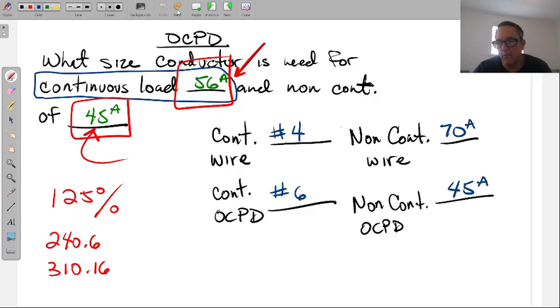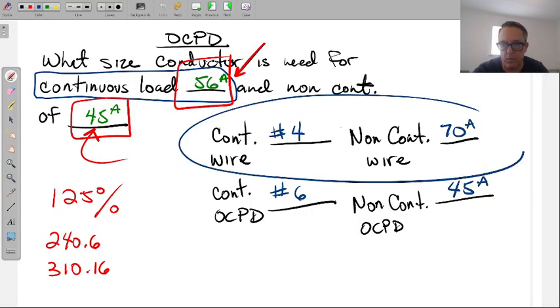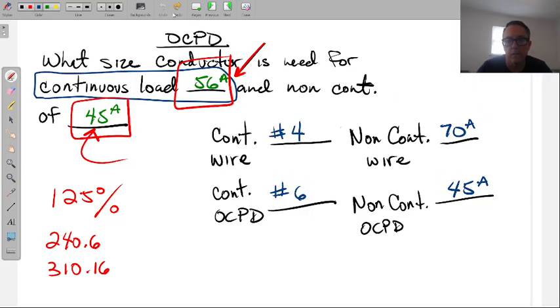I had a friend of mine who was taking some glass blowing, making those glass things. The teacher needed to have these giant kilns put into a shop. Okay, how do you wire this up? He said, I've never seen these things before. Information: continuous load. These things are going to operate for many hours. Whatever the amperage on that machine says, for a continuous load increase it by 125%, and then do this. Go find a breaker, a set of wires. These are all very useful.